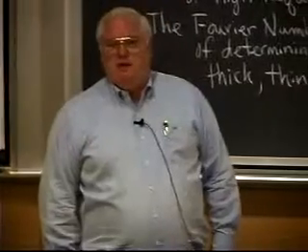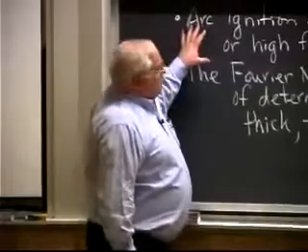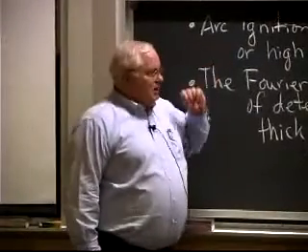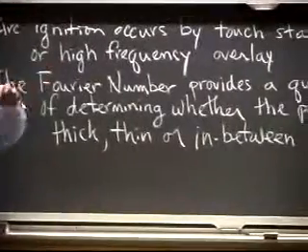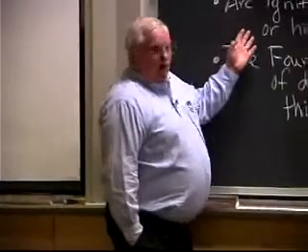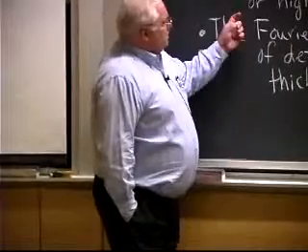Or November here. Okay, last time we talked about arc ignition and the fact that it occurs by touch start or by high frequency overlay. You've got to generate free electrons in that space in between. And by touch start, it's basically the resistive heating of little asperity contacts. And essentially, as you're breaking those contacts, the resistance goes up, and as the resistance goes up, the heating value goes up. The heating value goes up, and you can get to the vaporization temperature of the metal quite readily. With only 1 or 2 volts, you basically blow things apart as you're separating those things.